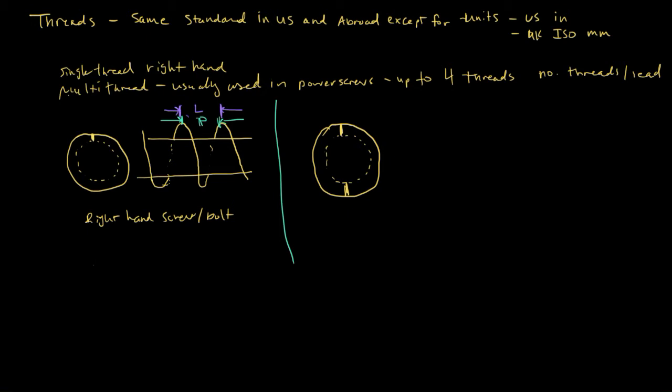So if we looked at the axis of the screw, and if we wanted to draw a left-handed lead in this case, then we could do this and come down here. So that would be a thread. And notice how the thread taper is now going down to the left versus over here where it's down to the right.